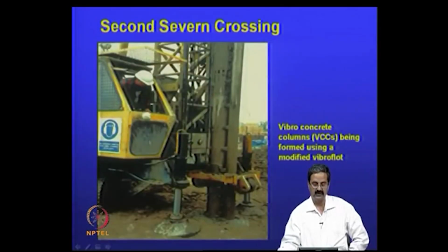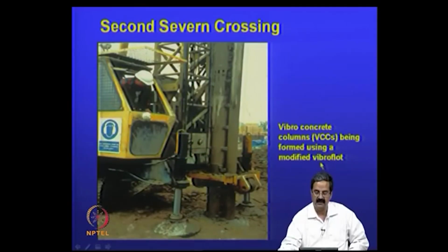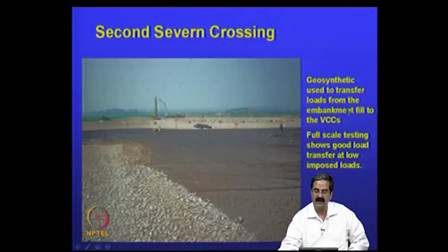They use a sort of stone columns, and for that, to transfer the load, exactly what they did was, we have seen how to design stone columns, but if you are able to place a sort of geogrid at the top like this, it can help in load transfer. In fact, the load from the embankment to the pavement to the stone columns could be less.